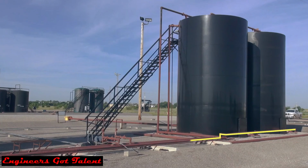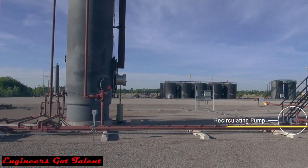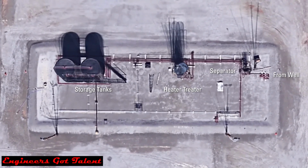This is the recirculating line, goes into the recirculating pump. From here it goes back to the inlet of the treater, runs through the whole treater again. So there's a line that we can bypass the separator, and then there's a line that we can bypass the treater, and then there's a line that we can bypass both of them. It's all done with valving.